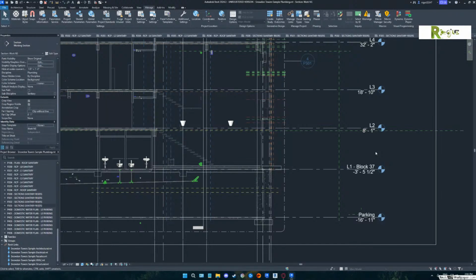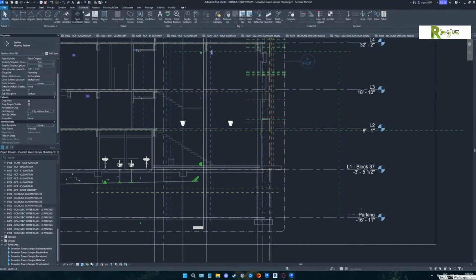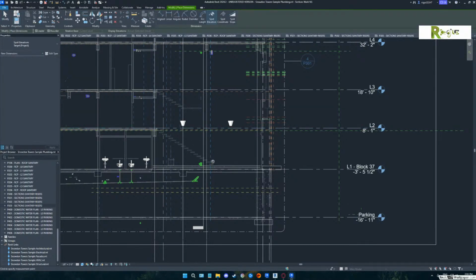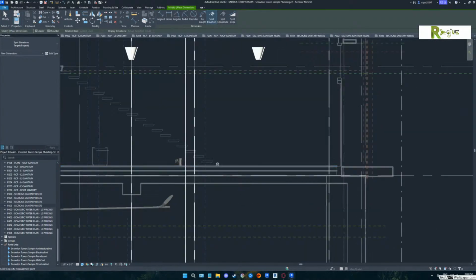You see the stairs coming down the sheet, right above your L1 block 37, right there? Put an elevation mark right on that floor slab at that last one. Annotate, spot elevation, right on the floor at the bottom. See, that's at -2. That makes absolutely 0 sense.